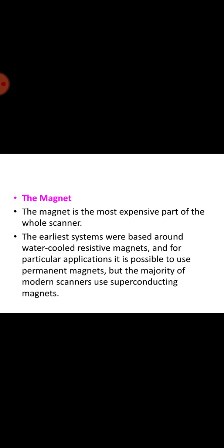Resistive magnets make use of large current carrying coils of aluminum strips or copper tubes. In these magnets, the electrical power requirement increases proportionally to the square of the field strength, which becomes prohibitively high as the field strength increases. Moreover, the total power in the coils is converted into heat, which must be dissipated by liquid cooling.